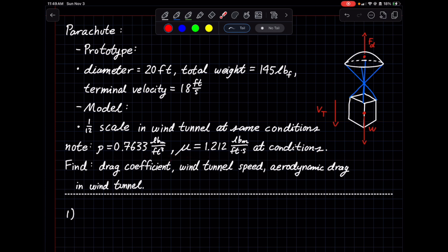Why did I get these instead of having a temperature? Because if you remember from video 1, temperature is one of our primary dimensions. We can express temperature inside of these two variables because fluid properties change with temperature and pressure, and as we were given the temperature and the pressure, we can now describe both of those in our density and our kinematic viscosity.